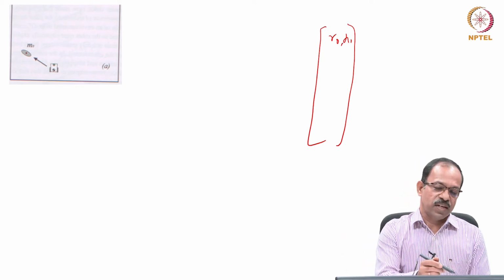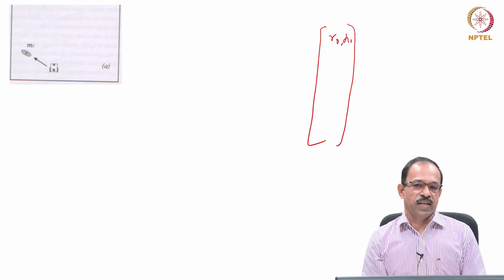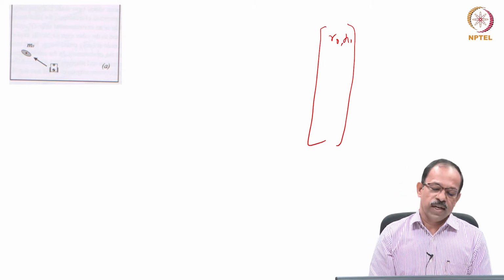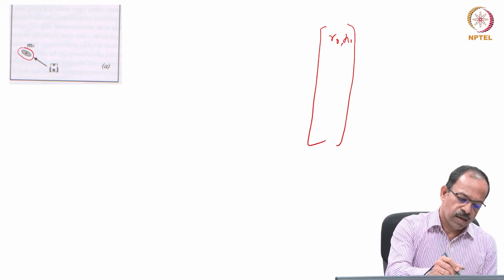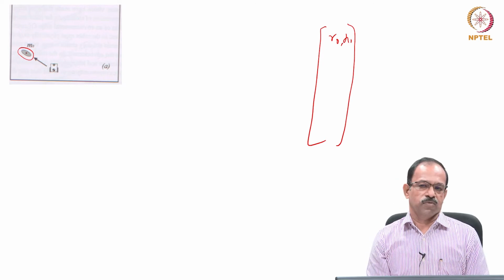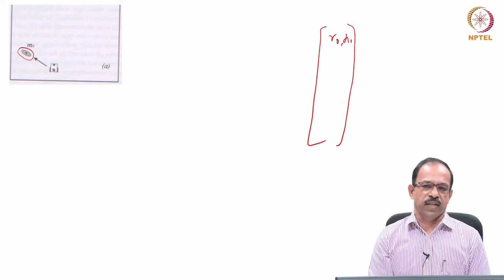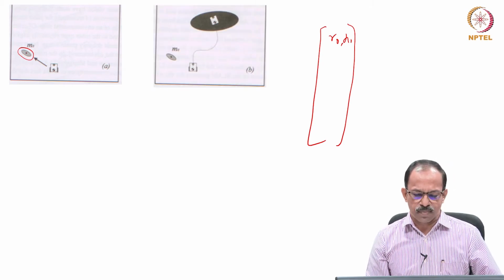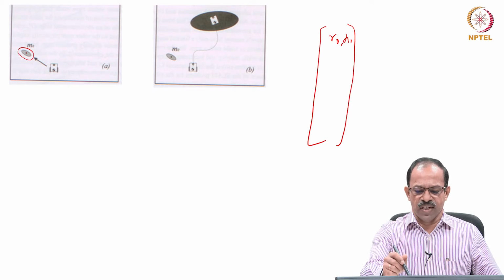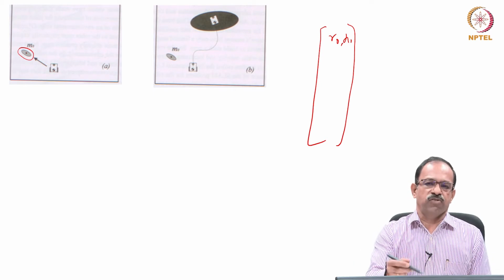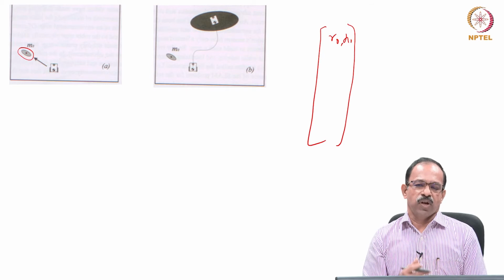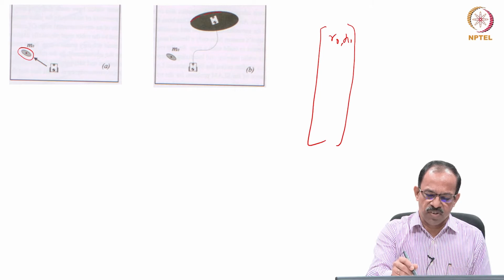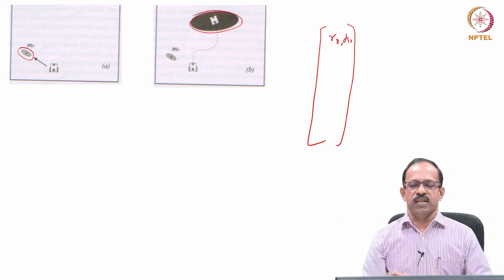And there is an uncertainty, because the robot position is uncertain and the sensor used is uncertain. It has uncertainties, errors. So there will be an error in the object position also, and that also will be recorded: how much the error is in the position of the object. And the robot starts moving further. As it moves, its position uncertainty increases because it only has the odometry. At every odometric calculation, the uncertainty increases. So the robot is very uncertain about its position, and that is why it is a large ellipse.